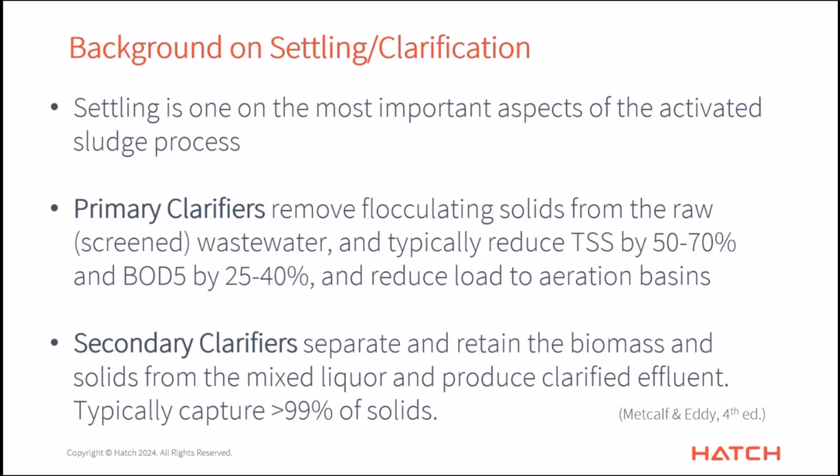Now, the secondary clarifiers, as you know, are there for a different purpose, and that's to separate out and retain that precious biomass that we've been growing in the bioreactors and bring that back as part of the mixed liquor. And by doing that, you're producing some clarified, hopefully very clean effluent that can go onwards and get disinfected and then head out to your receiving water body. And so those are designed, instead of talking about a TSS removal of 70%, we're talking more about, in the case of secondary clarifiers, capturing almost as much as you can.